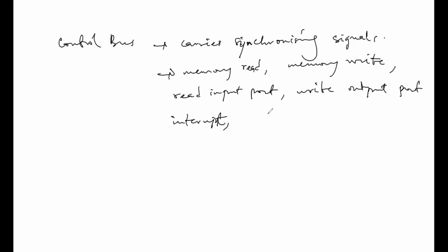So it should be noted that the system bus is a communication medium for data transfer, okay? And such data transfer is usually referred to as a bus transaction, okay? So a bus transaction could be memory read, memory write, input-output read, and so on, okay? And the bus transaction usually involves a master and a slave. So the master is the initiator of the transaction, while the slave is the target of the transaction.